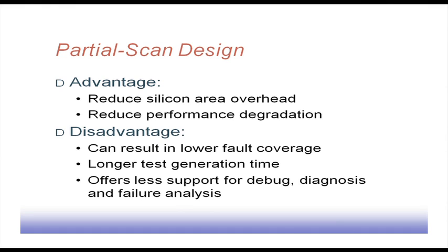Also, the support for debug, diagnosis and failure analysis is less, for the same reason that the entire circuit is not visible. Many of the flip flops will continue to be normal flip flops, so they are not visible at the output.